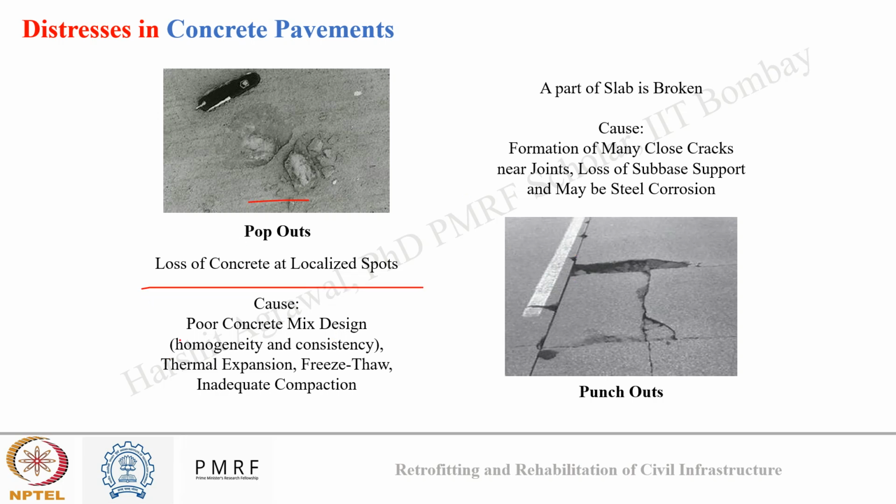They can occur due to poor mix design of concrete, thermal expansion, freeze and thaw, and inadequate compaction. Other reasons can be excessive loading or impact loading that may have been caused by some action at the roadways, which can also cause such pop outs.